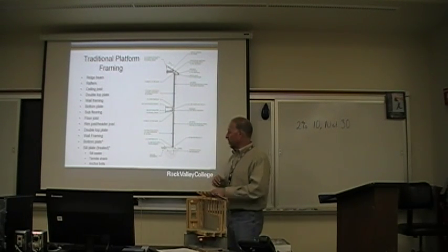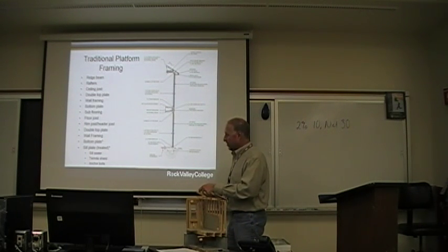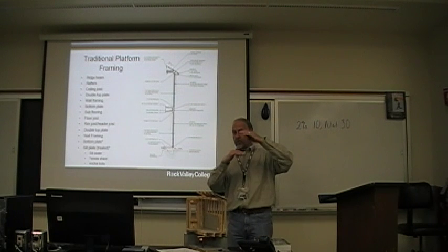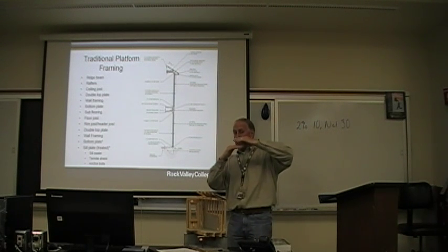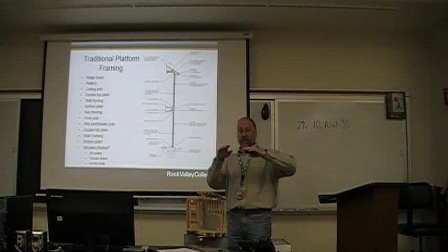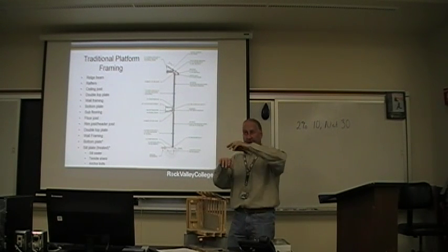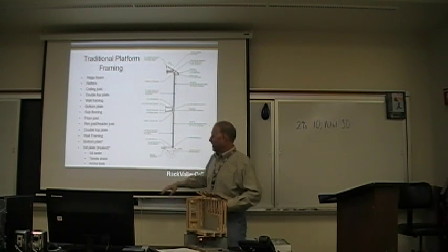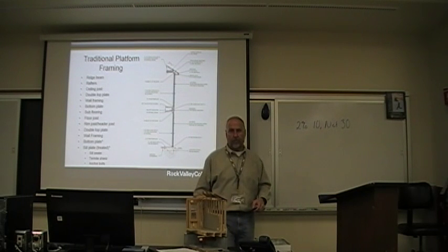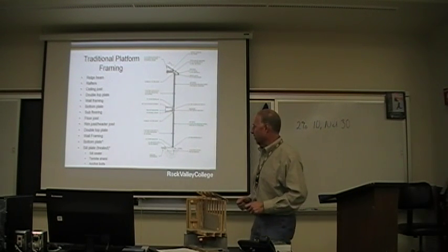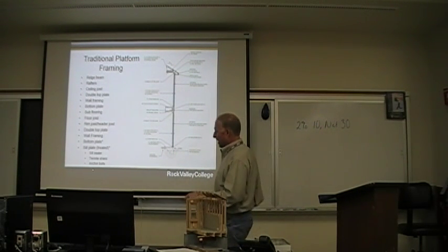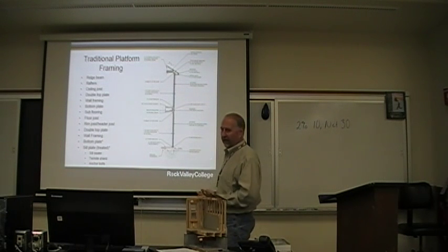But what's also incorporated in this sill plate assembly is a sill sealer that goes between the foundation and that sill plate in order to take up any voids or misgivings in the foundation. But then also, we need to incorporate a termite shield. We need to make sure those critters don't get up into our wood. And then, of course, anchor bolts to tie it all together.